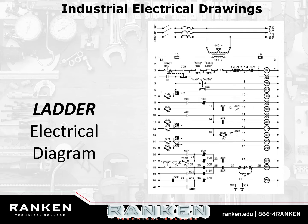Well, this limit switch is physical. There's a mechanical something that has to close that limit switch, right? A hydraulic cylinder has to go forward, or a conveyor belt has to hit a certain spot, or a chain has to hit a certain spot, or something has to be moving and get to a certain spot to move that limit switch. Once that limit switch closes, bang!